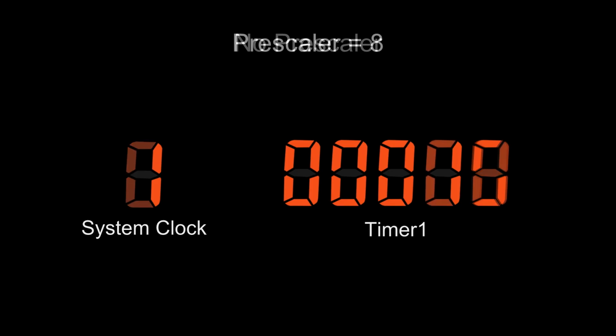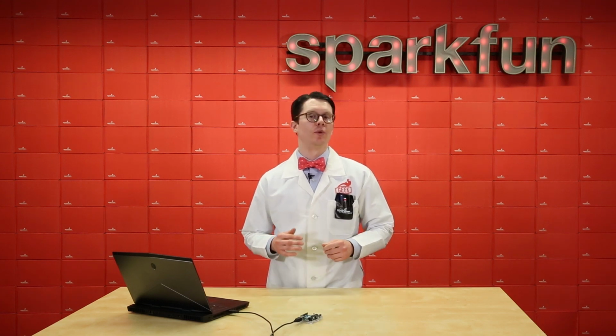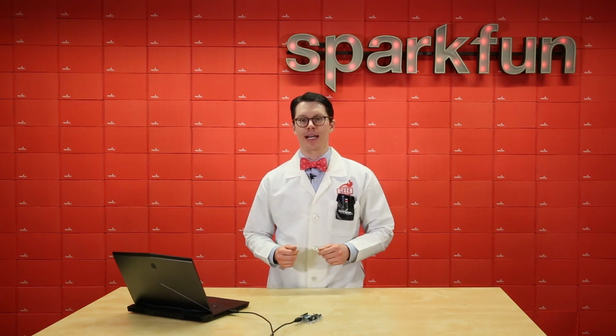We'll be focusing on timer 1 in this example. Let's say we set the prescaler to 8. Now, timer 1 increments only once every 8 system clock pulses. As you can see, we can play with these prescaler values to adjust how fast each of our timers counts.